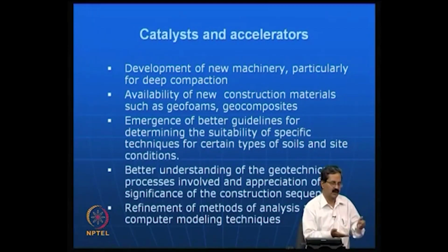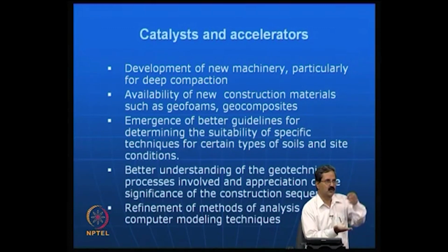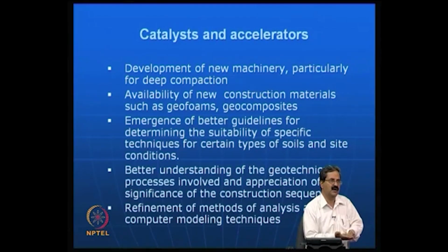You have a subgrade, a sub base, a base, and a wearing course. Whatever load comes on the wearing course has to be distributed, and when you calculate the load coming on the subgrade, that should be less than the bearing capacity of the subgrade. That is the principle.